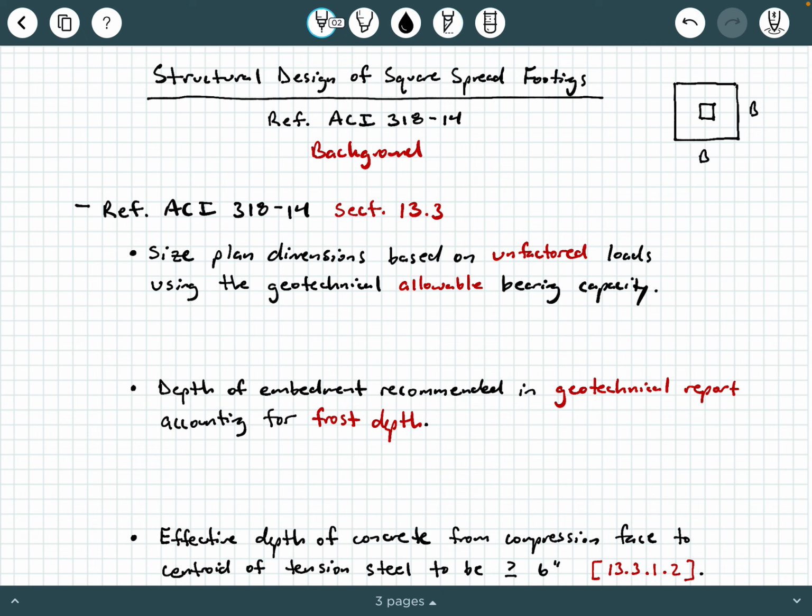So if we were going to look at a side view of this, we would have the column coming down like this, and then we have our footing like this. And that applied load is coming down through the column, and that's going to engage this bearing pressure here. So you're going to have this bearing pressure response beneath the footing, and this is going to be a uniform bearing pressure. We could just call it sigma of some sort.